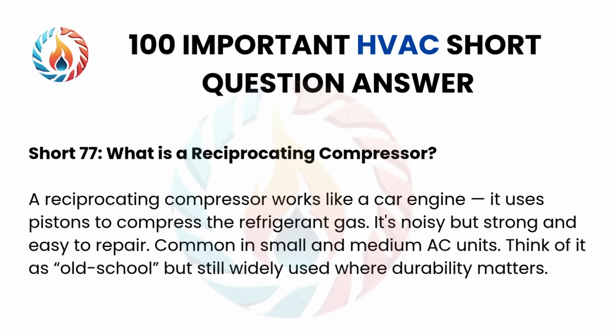Short 77. What is a reciprocating compressor? A reciprocating compressor works like a car engine. It uses pistons to compress the refrigerant gas. It's noisy but strong and easy to repair. Common in small and medium AC units. Think of it as old school, but still widely used where durability matters.